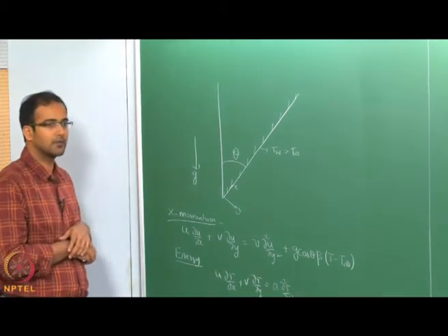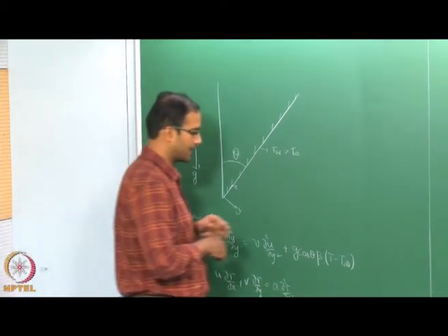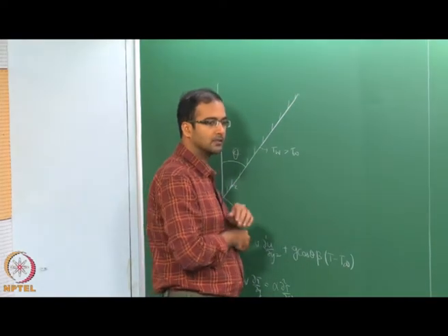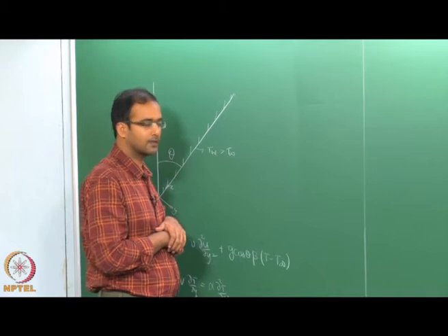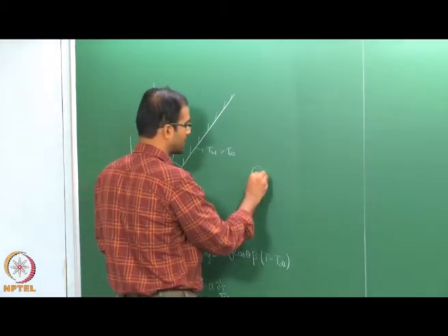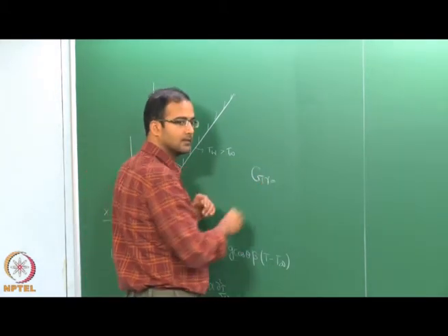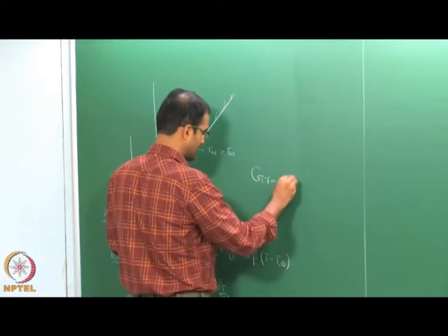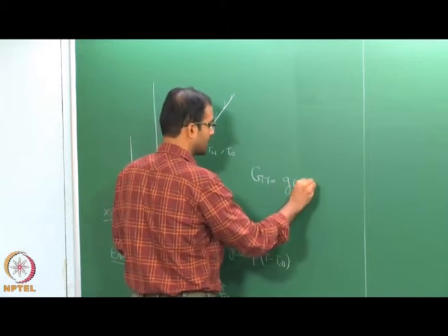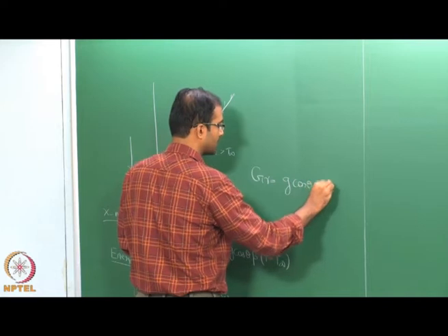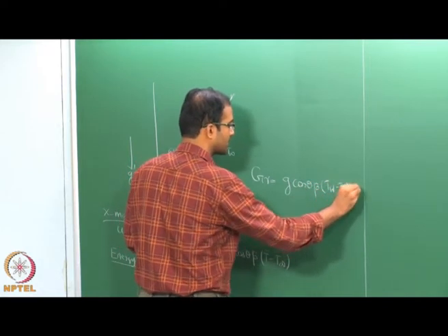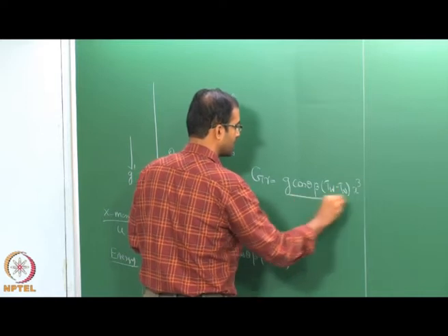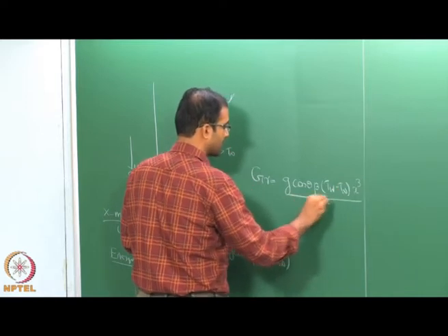Okay. So, therefore, in such a case we can have the same solution whatever we did for the vertical flat plate, and we will only redefine the definition of Grashof number. Okay. So, we will just include g cos theta into beta into T wall minus T infinity into x cube by nu square.